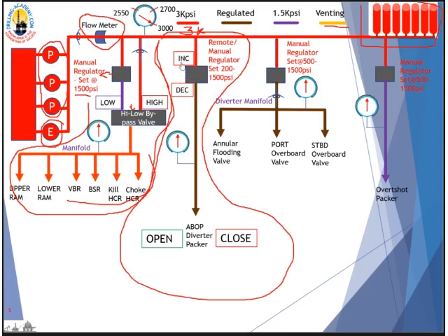You press a button from the remote control panel, or you can go down to the cooling unit and turn the valve handle. Here, imagine we are at the remote control panel, we press increase, the pressure in the line is increased. When we press decrease, the pressure in the line is decreased.